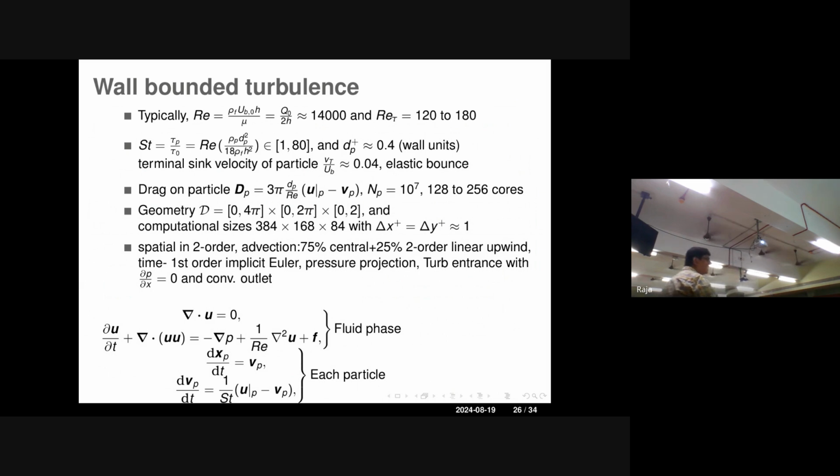No, it's quite easy. But the magnitude of forces, because this is for unit volume, is rho multiplied by g. So 1000 multiplied by g is something like 10 power 4, the local forces acting at every point. But the forces because of these turbulent fluctuations are at least 1 order of magnitude more than gravity. And gravity can be included, but not for this.